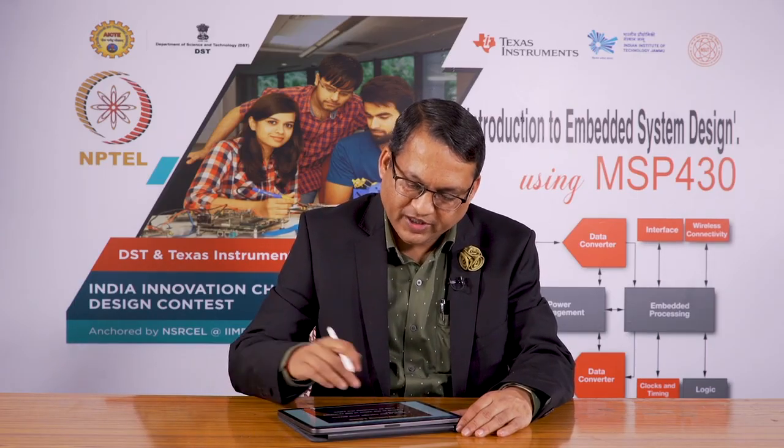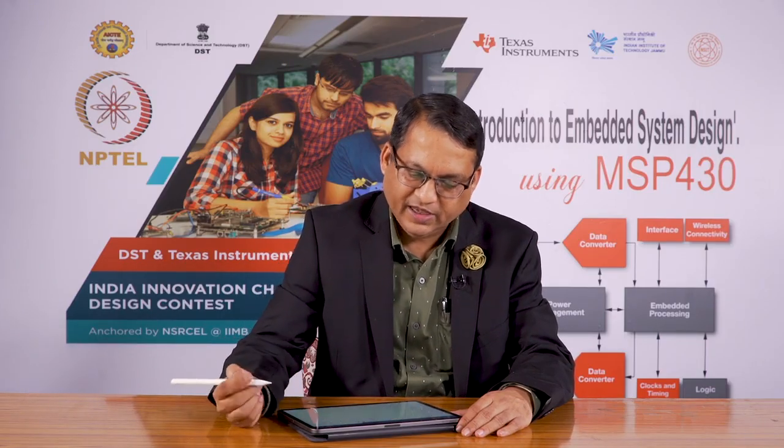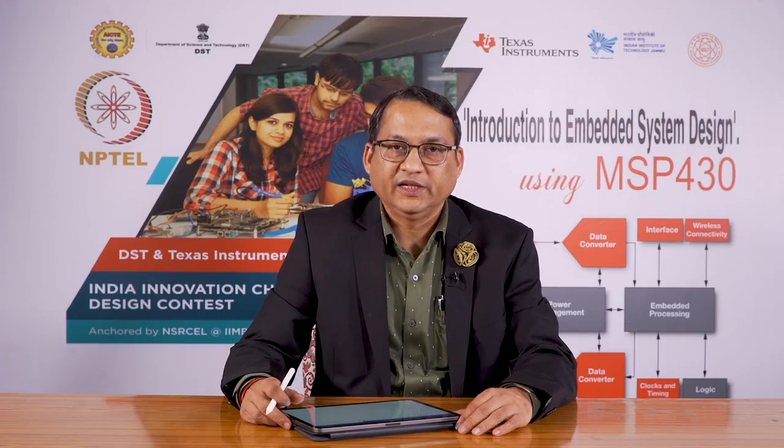First of all, for that we have to consider what is the voltage drop across the LED. Most of the time when I ask this question to beginner students, they say the voltage drop across an LED is 0.7 volts. For some reason they think that the LED is also a normal silicon diode, but that is not the case.